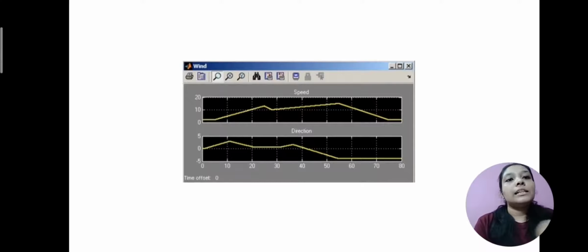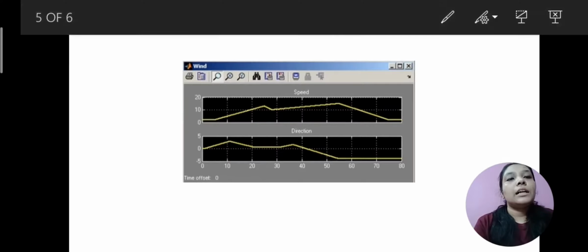Now, in this chart, we can see that while running the simulation, the wind speed at the beginning is too low. Once the wind is high enough, the system comes to life and the rotor gets turned on, and the system is going to accelerate to a certain speed. Once the speed is reached, blades will pitch in order to maintain that speed, so that the generator